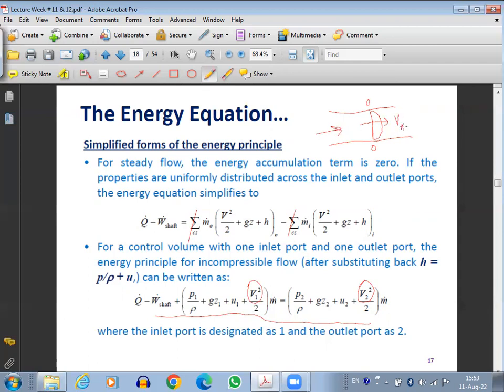So we'll have a V max here, and we'll have V minimum, which is actually 0 at the edges. Which velocity are we considering here? It's not V max, it's not V0. We are considering the mean velocity, a hypothetical value of velocity which is going to have the same effect as the actual velocity. But this hypothetical velocity is going to be uniform throughout the entire cross section.